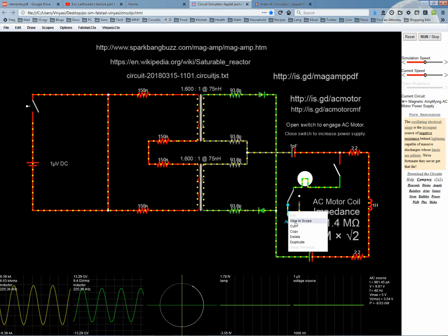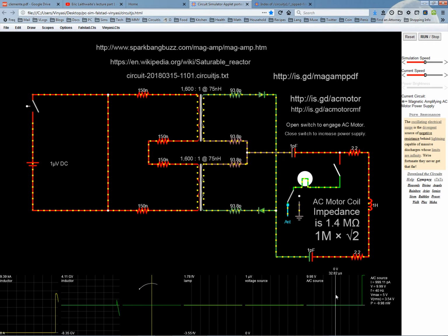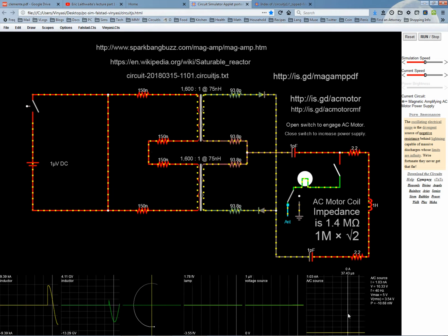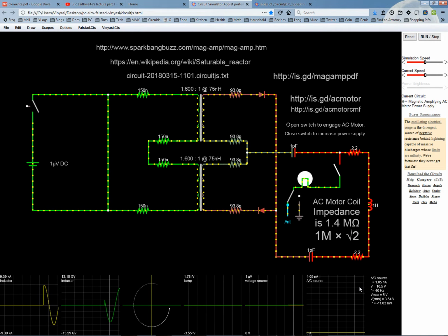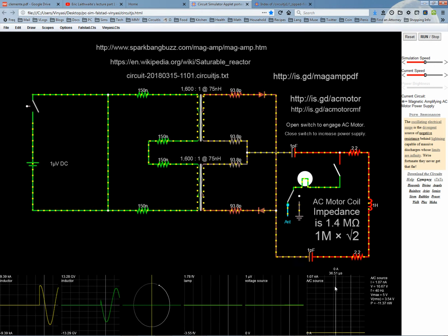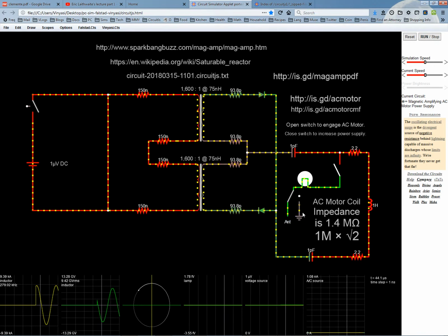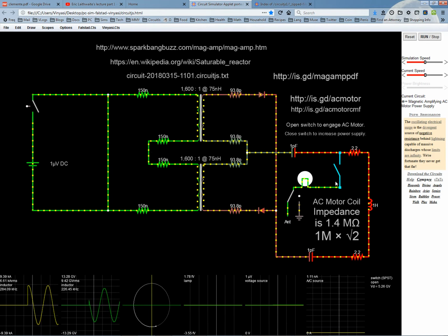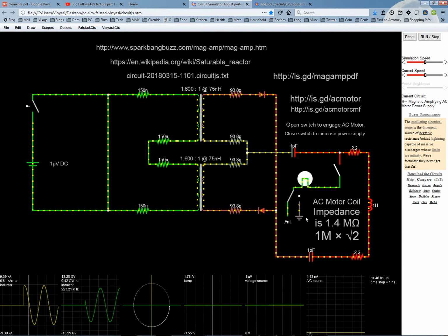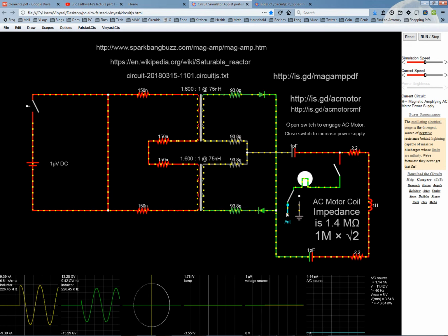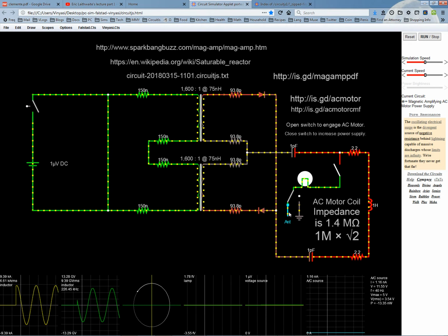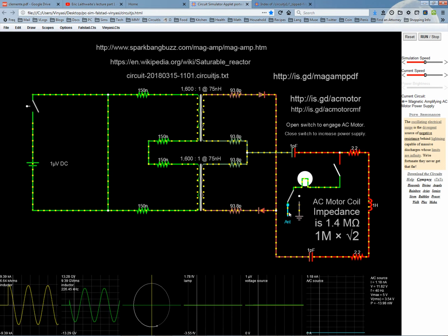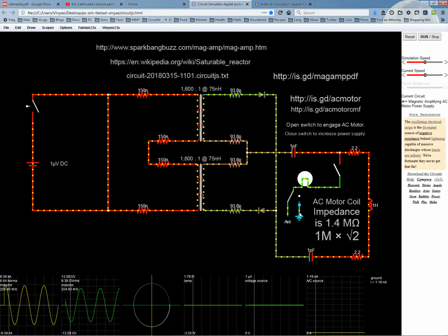But it looks like the aerial might be charged. Yeah, there it is. It's got 10 volts, which is not surprising, and its amps is 1 nanoamp. So once it switches over to the aerial and then it switches out the aerial, you're not really putting out any radio interference. So probably it'll never happen. So everything I said about an ionic generator may not be necessary in this instance, but we do need a reference, and the aerial and the ground serve as references for the circuit.